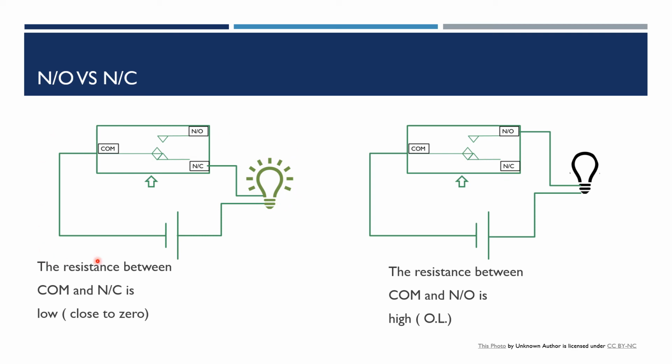So this is the case for the normally closed. The opposite is the case for normally open: if you start the connection with normally open, obviously the circuit is not complete, no current reaches the lamp, so it starts as an off lamp. Once you apply some pressure and reach the upper limit, the switch goes up until it reaches this limit and the circuit is complete, then the lamp is going to be on. So this is the difference between normally open and normally closed in a circuit.